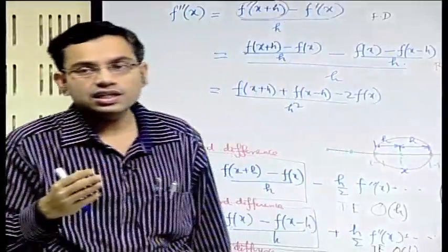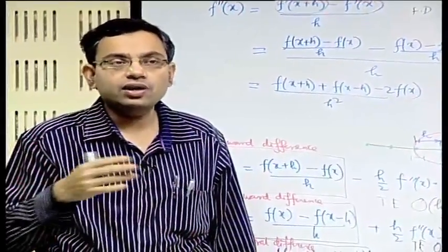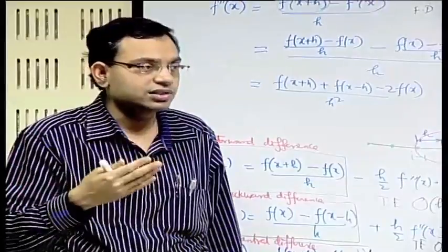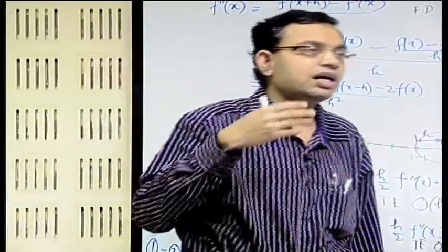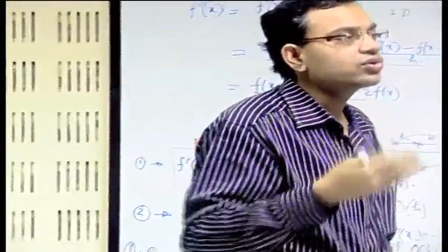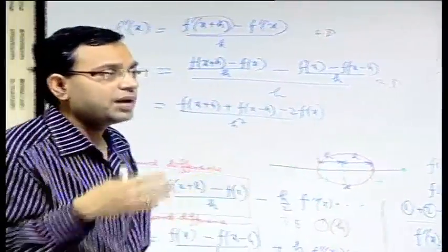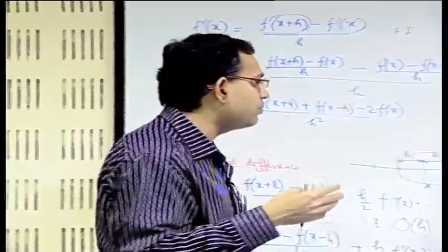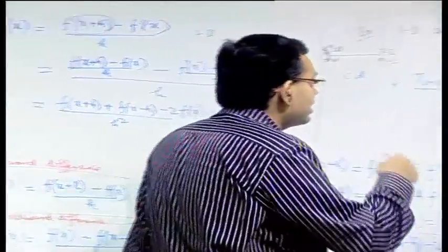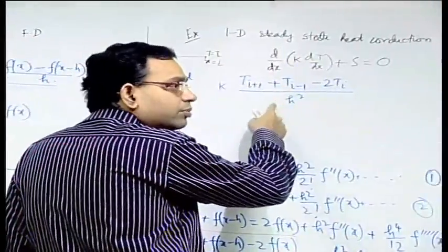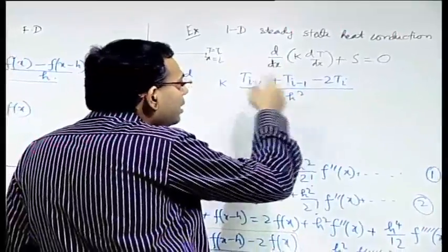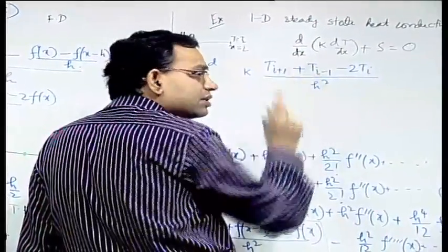It is not necessary that everywhere you use fine grids; that will unnecessarily increase the computational cost. So, wherever there is a less steep gradient you use coarser grids. It is possible and very much practical that in a particular problem you have non-uniform grids. This example is an illustration with uniform grids, but similar algebra can be arrived at with non-uniform grids; the expression will be different.